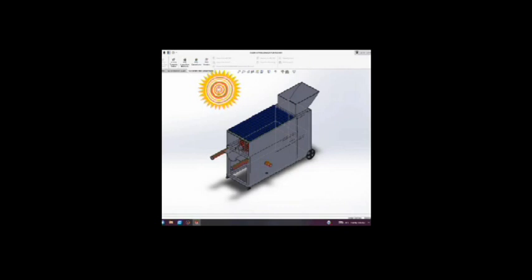To actuate the servo to open the outlet of fine sand, whenever the sensor observes a low distance reading due to an obstruction in its line of sight. When a container comes below the fine sand outlet and obstructs the sensor's line of sight, the Arduino board receives a low distance reading and instructs the servo motor to actuate and open the outlet.